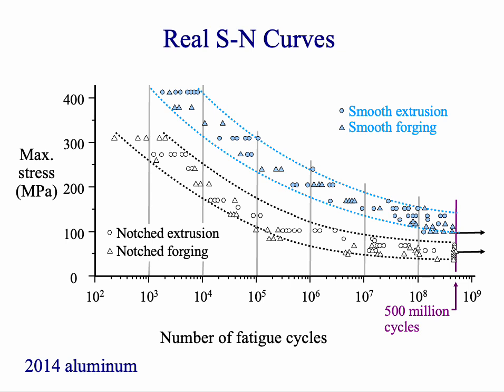When I worked in the lab in the light axle division at Dana Corporation, design engineers would wander in from time to time asking us to explain why the scatter in their fatigue data ranged by a factor of 5 from lowest to highest. And we would tell them that they were darned lucky. A factor of 10 is the best you can usually hope for. The reason the engineers' data didn't have more scatter is they didn't run enough samples.